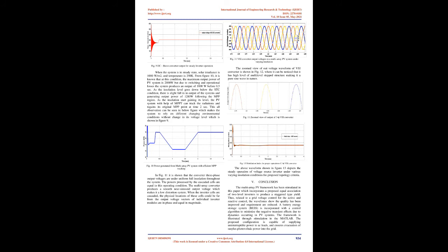Active power is supplied by the battery as long as the terminal voltage of the battery is above the battery voltage that represents the minimum state of charge. The charging current controller outputs a current component corresponding to the amount of power required to increase the battery terminal voltage to a value that represents the maximum state of charge. The net battery current is derived as the sum of discharging and charging currents. The reactive power component I*D for this design was maintained at 0 so that the battery does not supply reactive power. This component can also be varied.